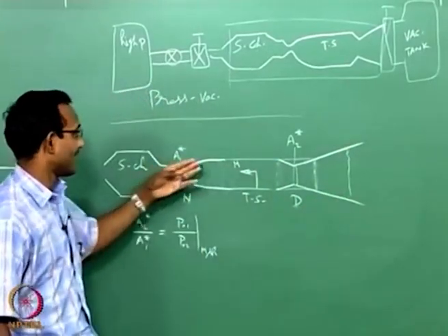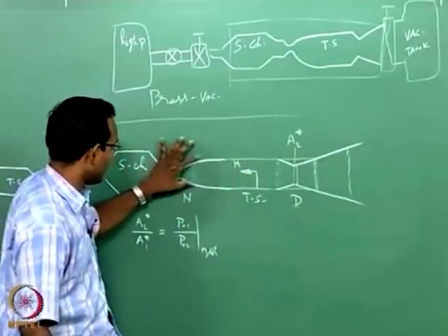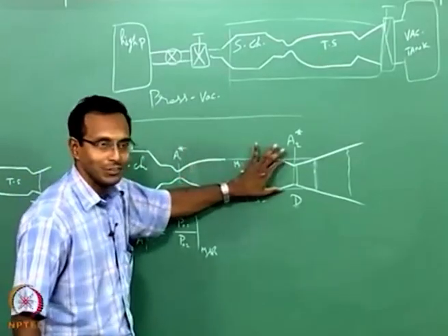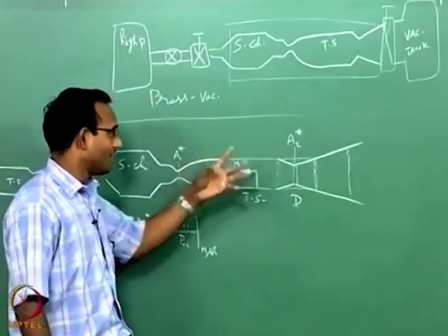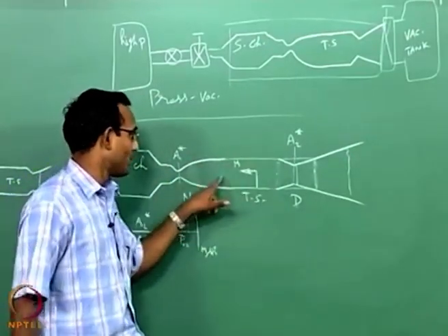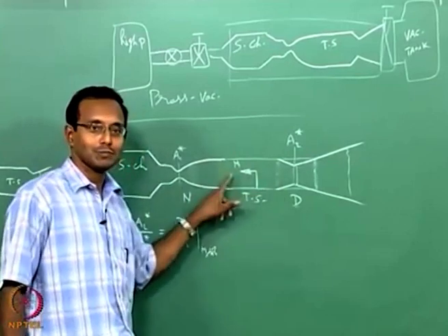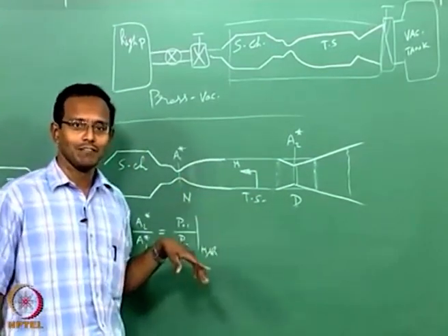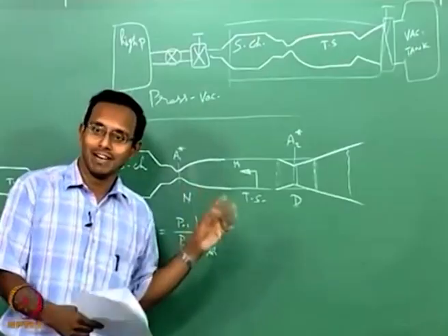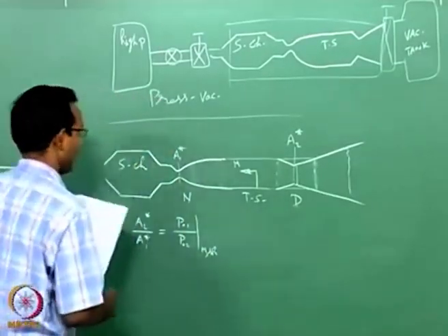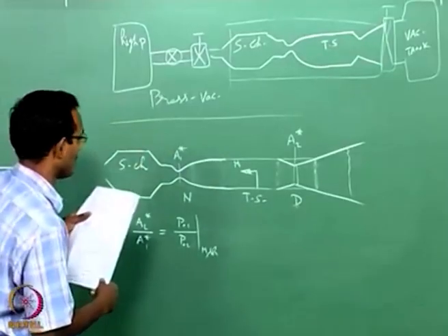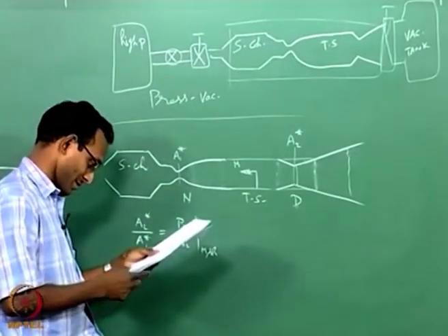This is actually an extended nozzle if you think about it, just a CD nozzle, just a straight portion in the CD nozzle and then a divergent portion again, that is all I am having. Even that will work. I have a straight section where I know my Mach number is going to be constant, and I will use my model in there, that is good enough. In fact, in our GD lab in IITM we have one such facility for Mach 2, where we do not use the second throat all the time. Okay.